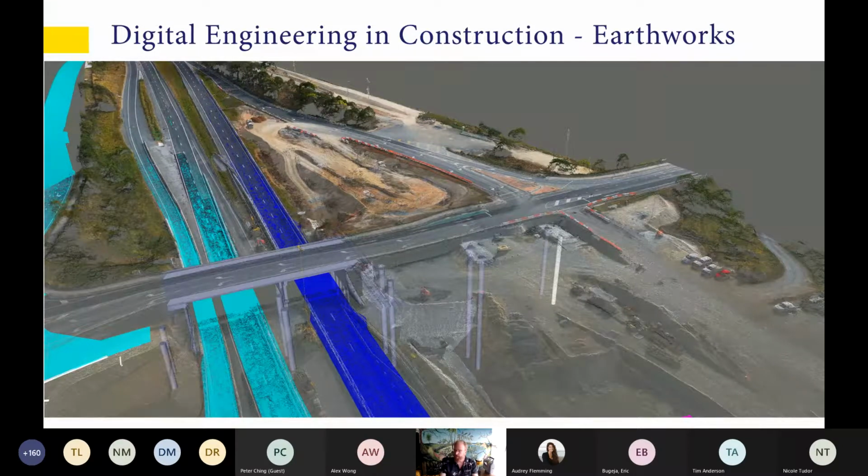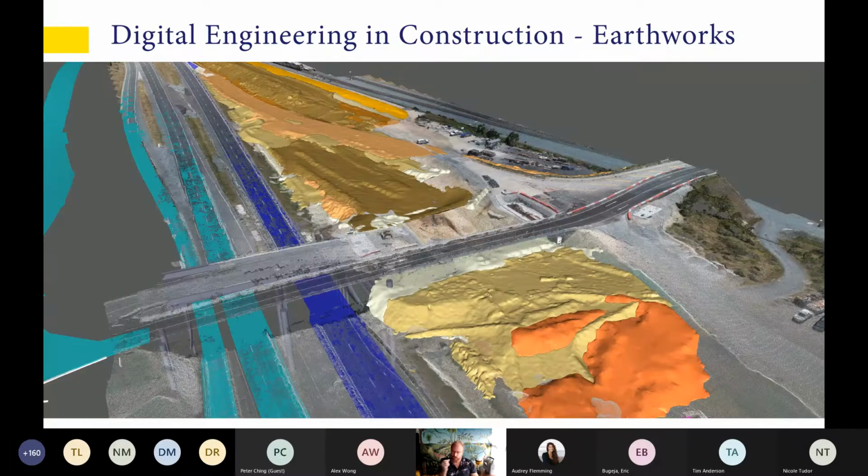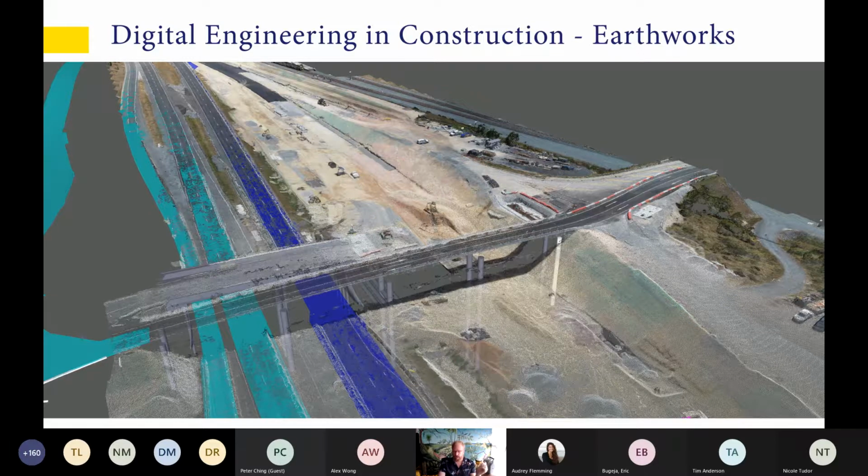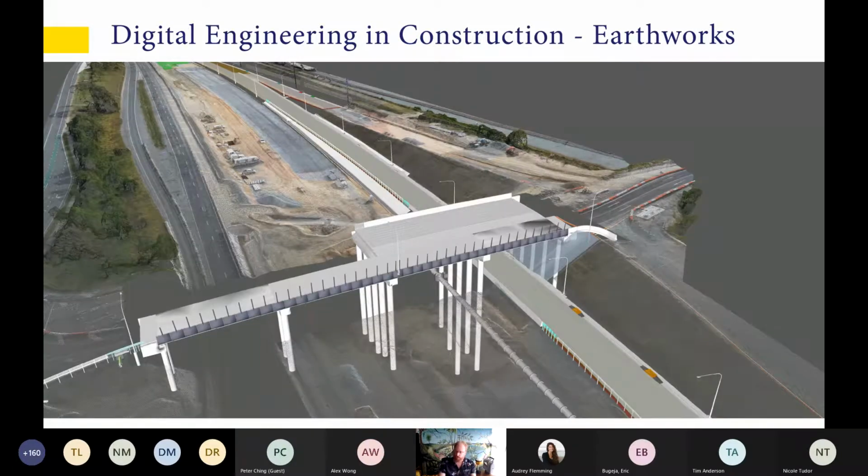Another thing we did trial at one stage, which I want to talk to Dwayne Rosie about a little bit further, maybe later, is some of the Earthworks stuff. What we did initially was follow the traditional pattern of doing surface-to-surface Earthworks volumes month to month. That's like falling off a log, more or less. Because you've got the surfaces there, you can easily create those as discrete watertight mesh objects. You can store information against them, obviously, but all you're really doing is showing where the dirt used to be and where it came from. Whereas we probably want to know more about where it goes and what subsequent uses there are as well. So there was some discussion about potentially using block models for that sort of thing. Obviously, you model it all the way down to the lowest cut and then backfill it with all the pavement objects and everything like that.